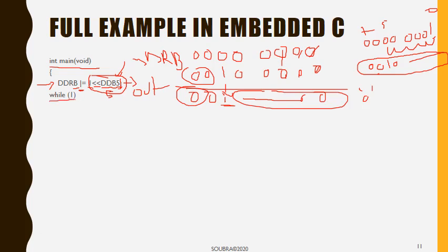Now I have a perpetual loop, and in embedded systems it's all about perpetual loops, and we're going to talk about those in the upcoming lectures. And check what I'm doing here. It's exactly the same thing, the same bitwise operation. However, I'm dealing with pin B7.